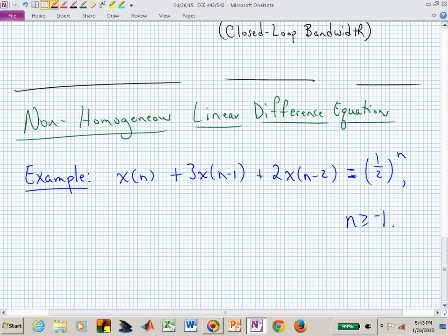But now we have 1/2 to the 1, and 1/2 to the 0. We start at 1, we go down to 1/2, then we just start chopping that down. That's an exponential decay in discrete time. 1/2, 1/4, 1/8, it's shrinking, but you can see this envelope of values that we're shaking the system with. We're kicking the system, but not with a step, but with something that decays exponentially with n. That's what 1/2 to the n on the right-hand side is doing.